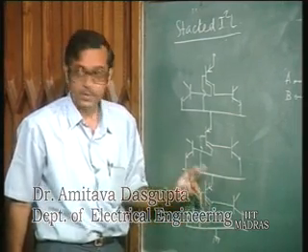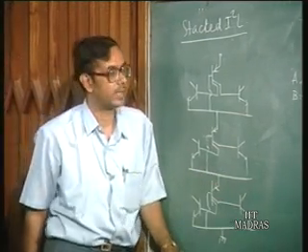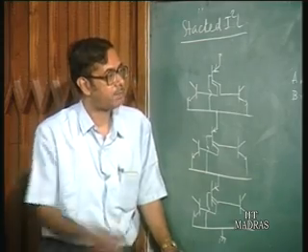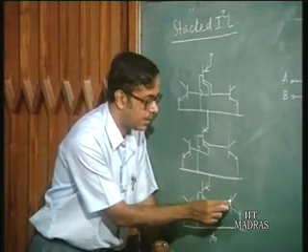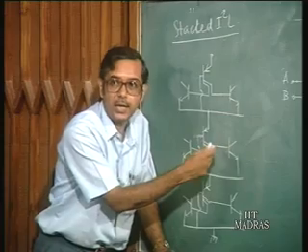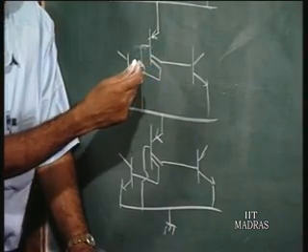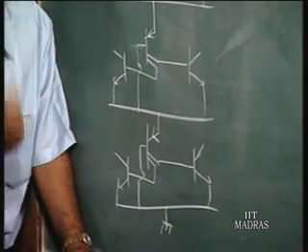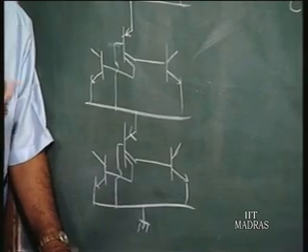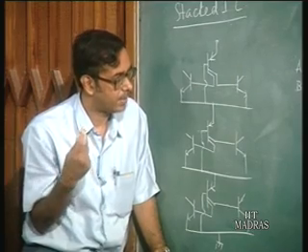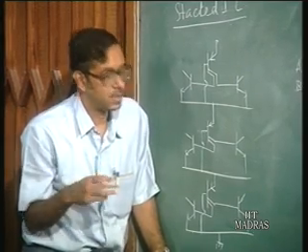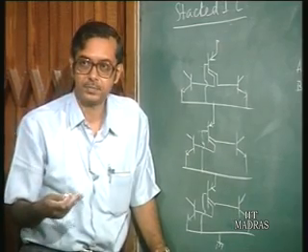Just one further point on this stacked I²L: is it possible to have the output of one level going as input to the other? All right, it is possible. The only thing is that in some cases you may have to do a level shifting.